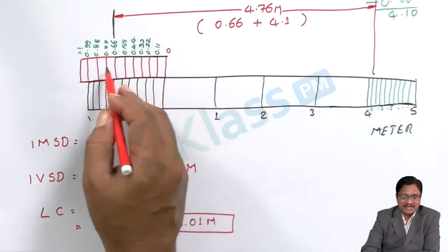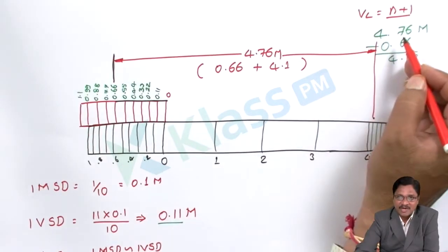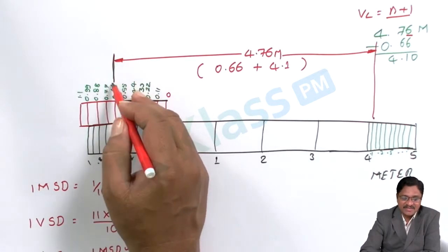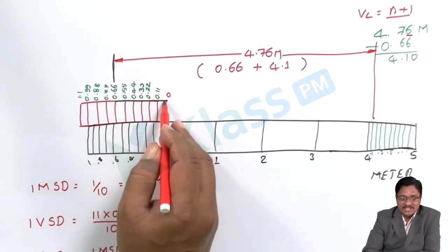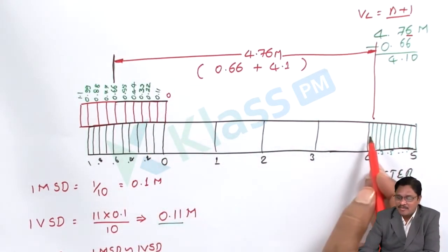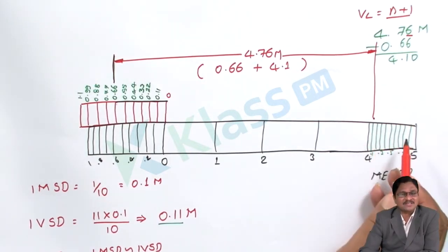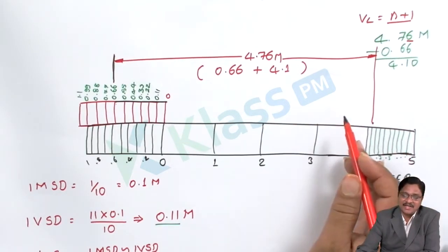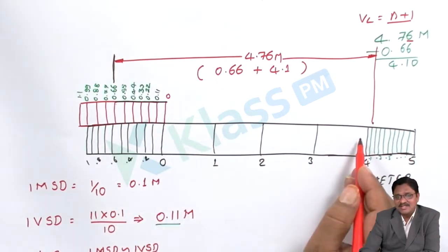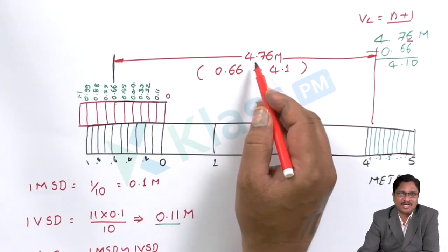Once you identify the vernier scale division value, write all the digit values. Next, what dimension is to be marked? Check the end digit where it is matching, and take that division as the first extension line. From that, subtract the distance taken on the vernier, and the remaining length has to be moved along the vernier scale. Where you need subdivision in that region, subdivide once again and identify the leftover distance on the main scale. By adding the vernier scale length and the main scale distance, you can represent the total distance required as per the problem.